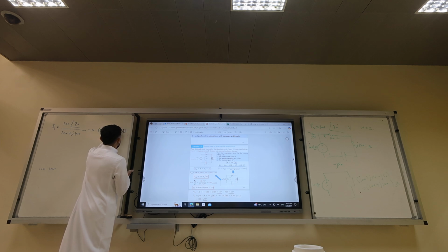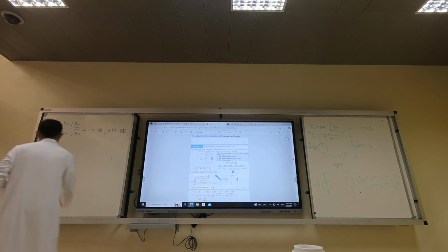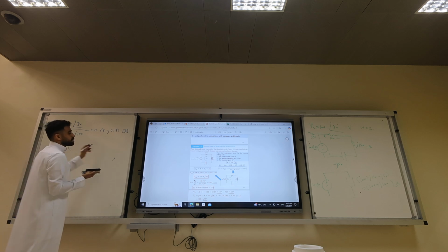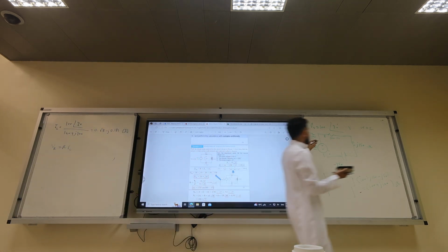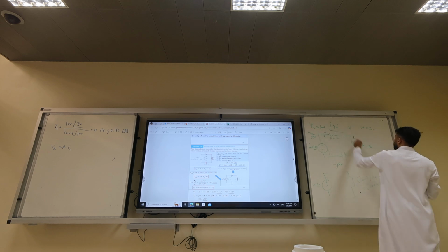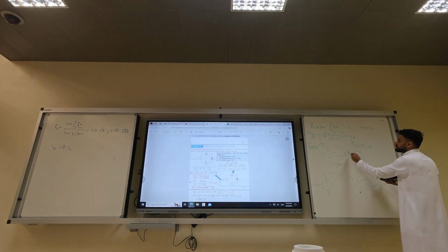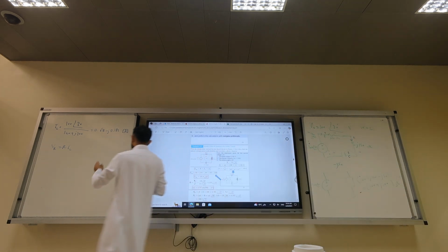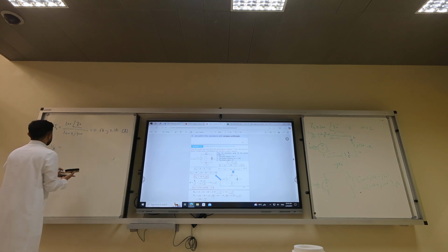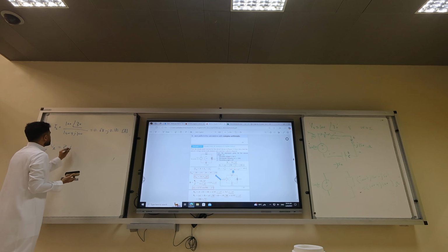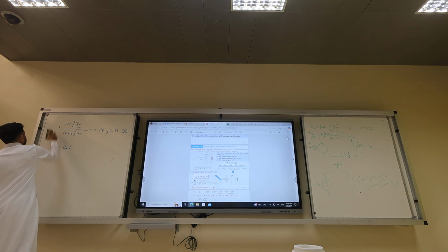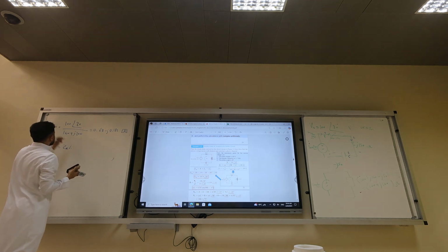So, what is V sub R? V sub R is R times I sub L, right? Passive sign configuration, do we have any issue with it? Plus minus, plus minus. The current always enters from the positive. So I'm going to write a better formula. V sub R equals Z sub R times I. We call this I, not IL, just I.